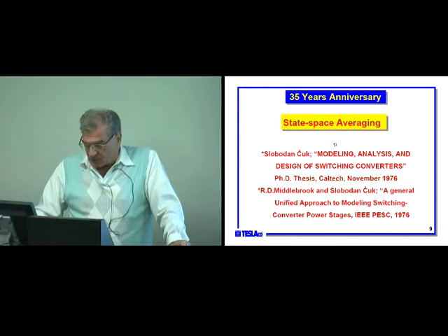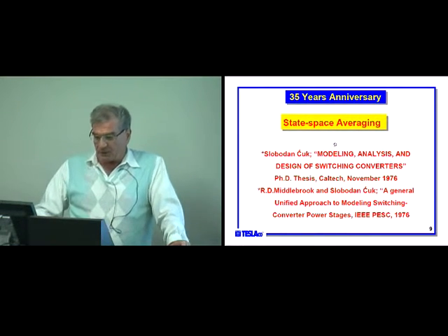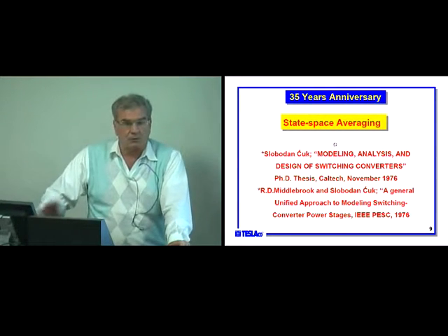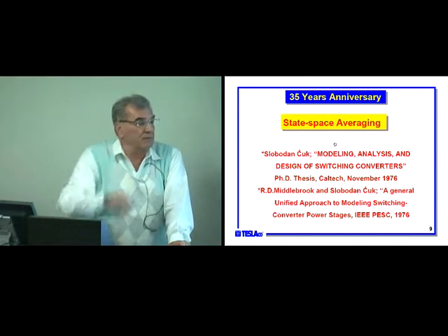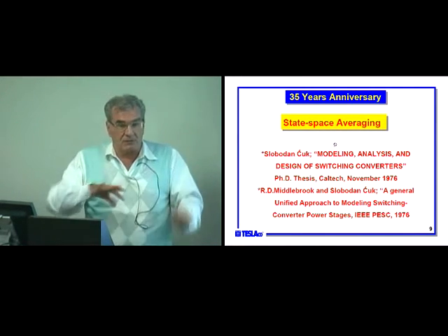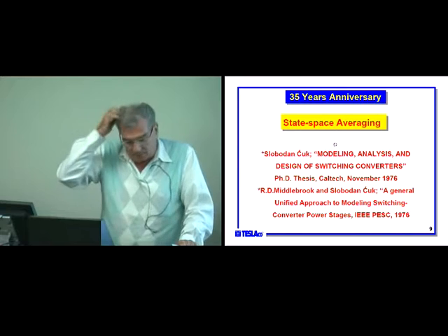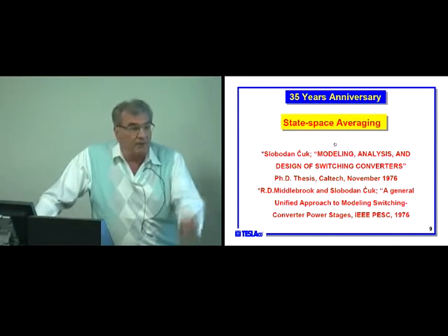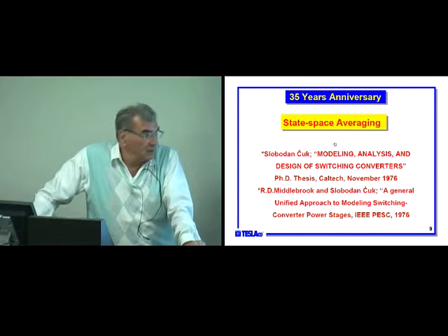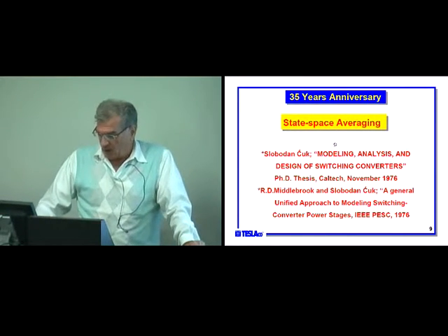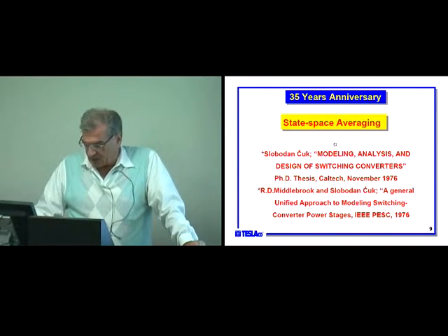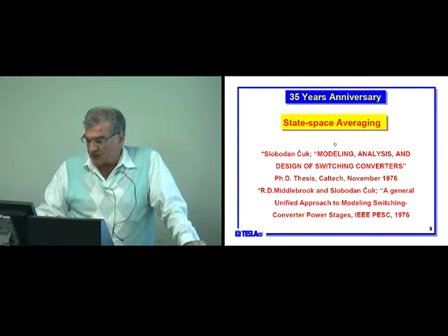So surely there was a need for a university there, because even for control system people, there was a rather special problem: how to control and model this switching converter system. Inductors, capacitors, switches, operating in a repetitive fashion, how do you come up with a simple circuit or model? So here, in 74 to 76, as a part of my thesis, I did a new method, what's now called state space averaging, considered one of the standard methods.